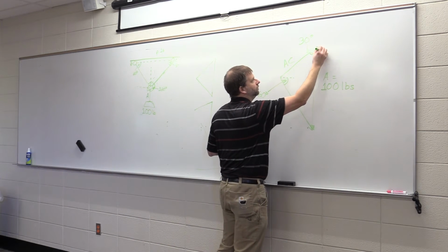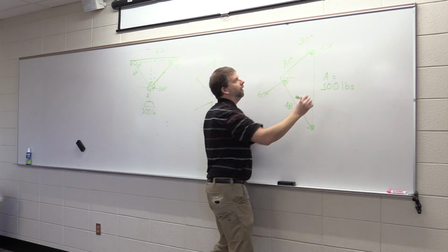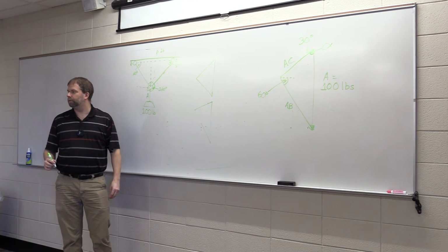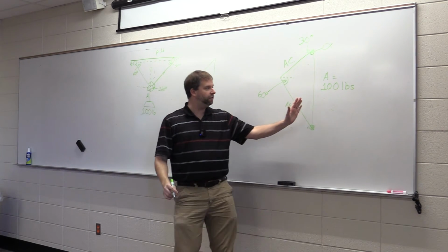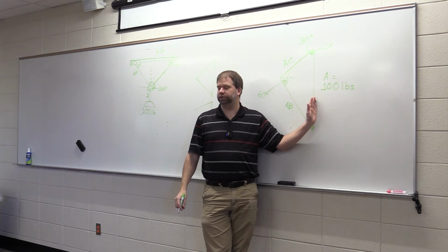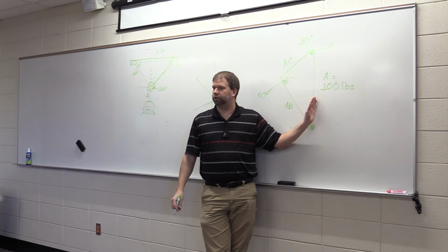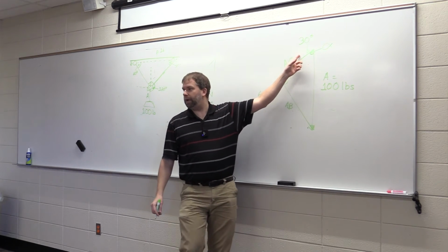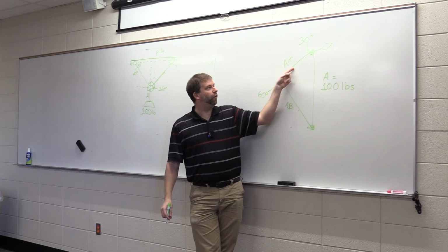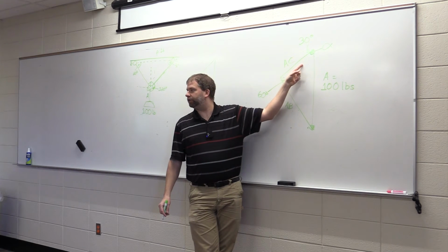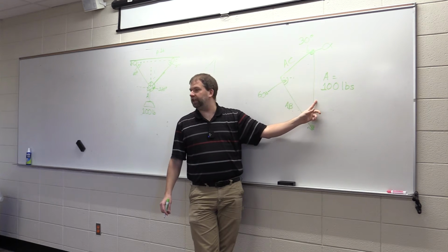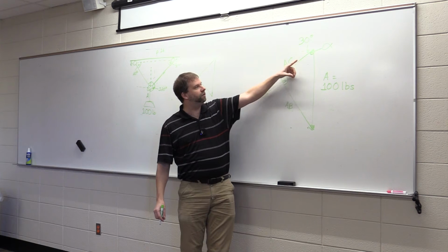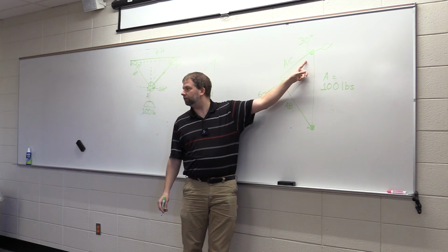We'll call this alpha. Why is it going to be 60 degrees? Yeah, we said this thing is perfectly vertical, despite my poor freehand drawing, right? And we also knew, Matt told us, that this force is applied 30 degrees from the horizontal. So if this thing is perfectly vertical, and this angle is 30 degrees, alpha has to be 60 degrees.